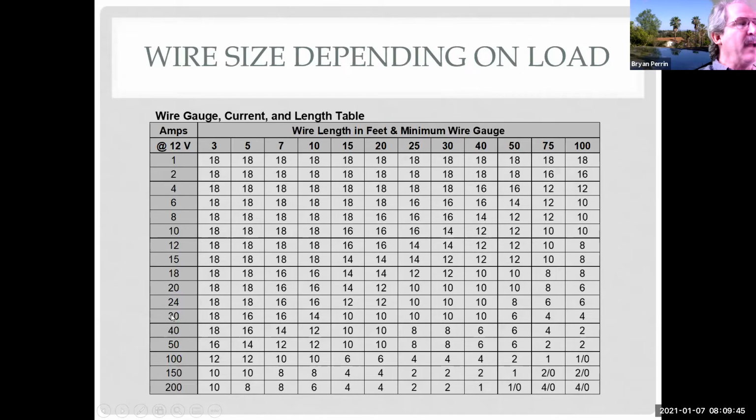So as a rule, for 15 amps, we use 14 gauge wire. And for 20 amps, we use 12 gauge wire. That's a good rule of thumb. But you can see here how manufacturers get away with running some smaller wire sometimes for very short distances. So this is a chart that I put in here, going with the question you had, Alberto, about, hey, do we have this?